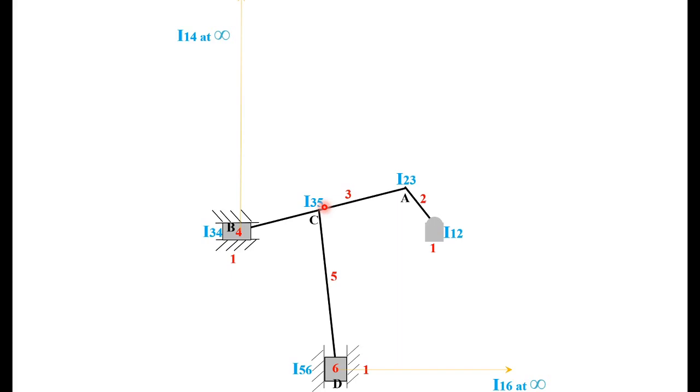The next thing is you have to locate the required centers only. Since the question is to find the velocity and no other things, you should locate only the required centers. Do not start locating all the centers. That is not the way. Since the instantaneous center location is not the objective, the only objective is to find the velocity of slider D. Again, remember how will you proceed? Now we have the velocity of A. So this is point A and we have the velocity of A.